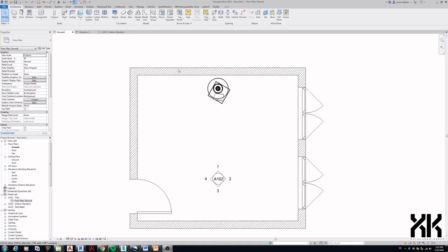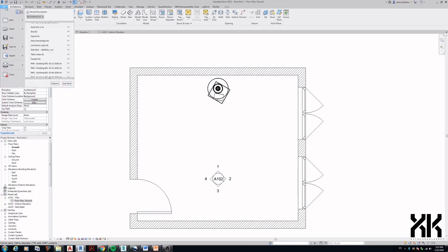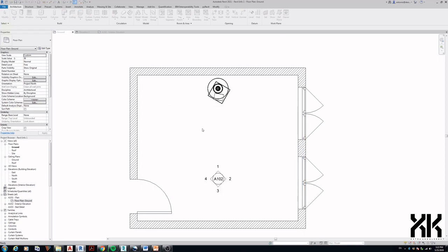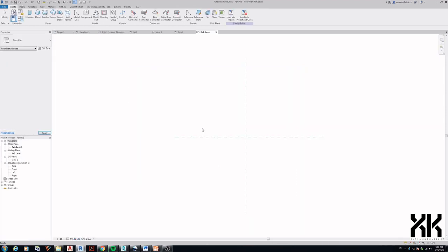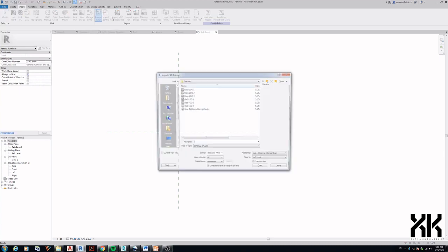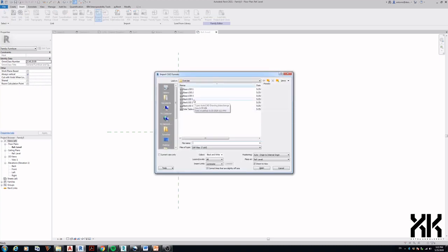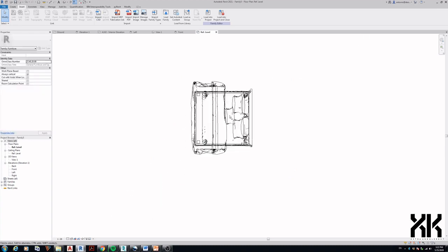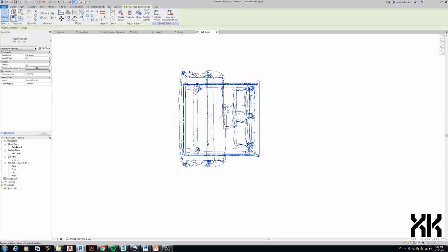In Revit, create a new family for example 2 and do the same process to generate detail levels. Every time you insert the DXF, assign the detail level before inserting the next DXF.